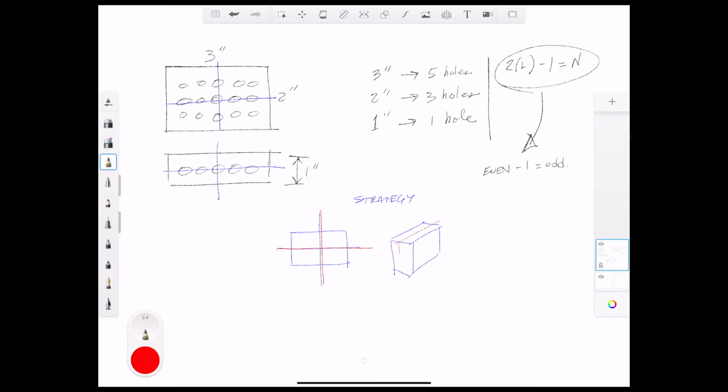I'm going to put that set of planes right in the middle. So I'm going to extrude out from both sides in order to get that to work right in the middle. And I need to think now a little bit about my default part. In order for me to be able to ultimately have a 4x4x4, it will help me when I'm making this to get all those features into the first version of this part that I create.